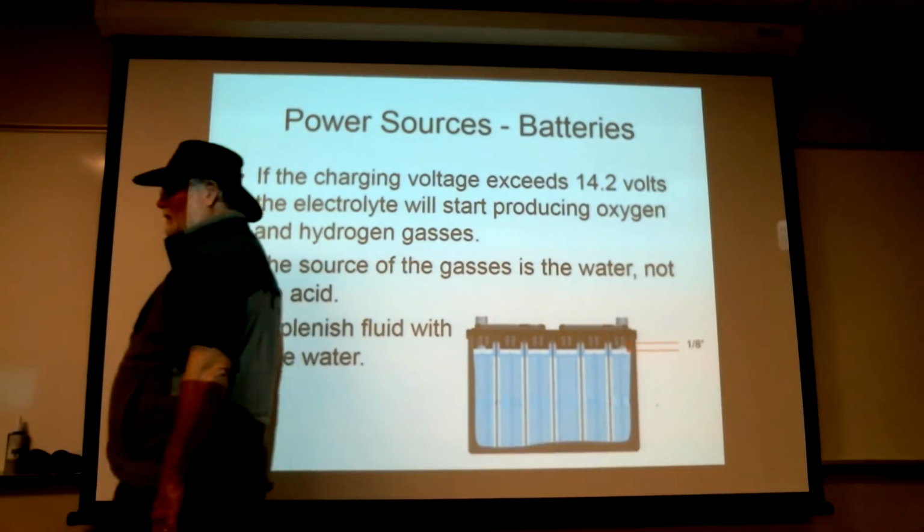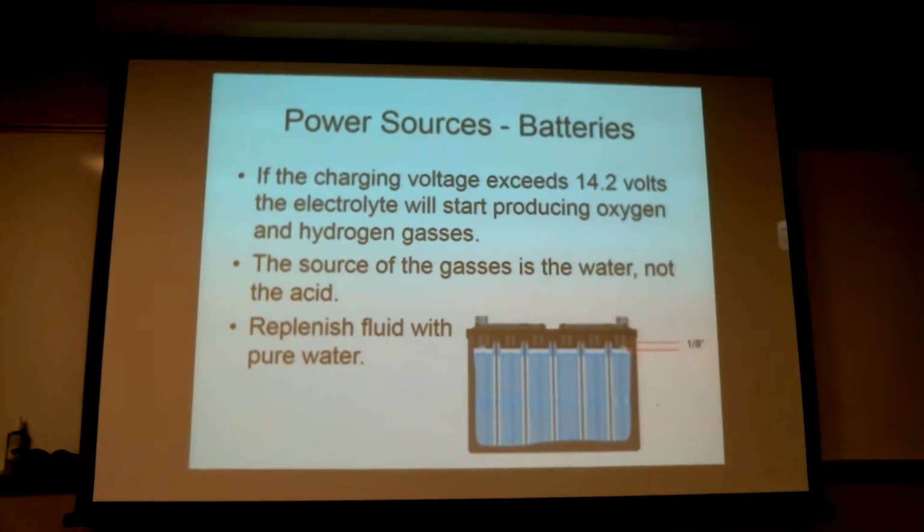Which is why, if you've got a dead battery and you're not in a hurry, the bad guys aren't chasing you, I highly recommend pulling the battery out of the vehicle, cleaning everything up, servicing it correctly, and charging it overnight, that kind of a thing.